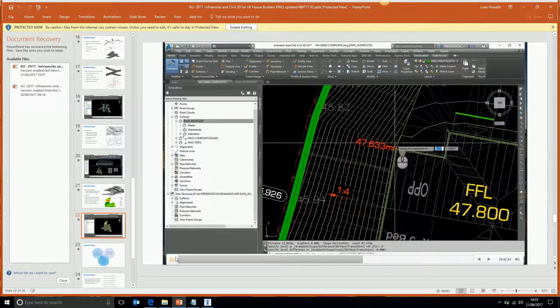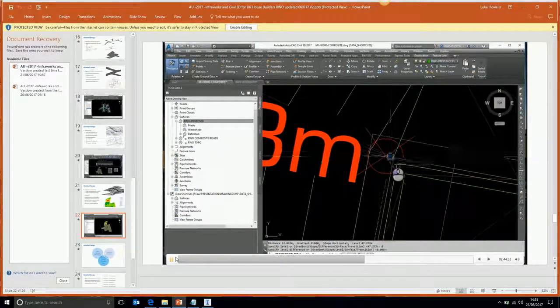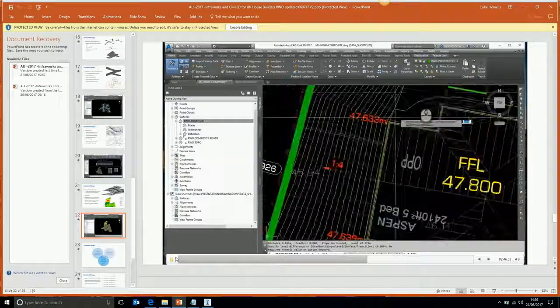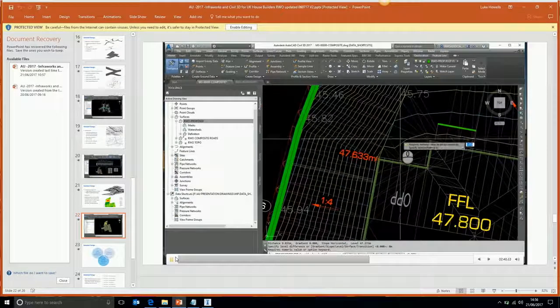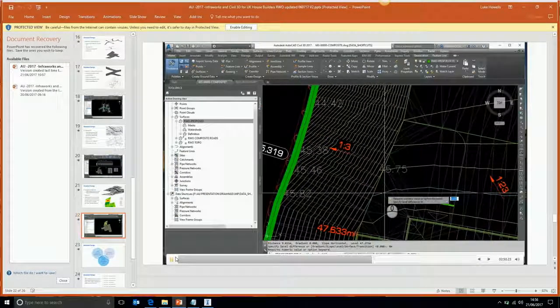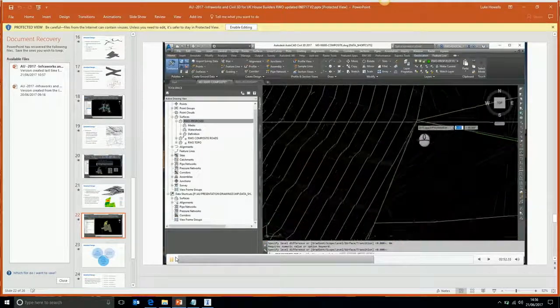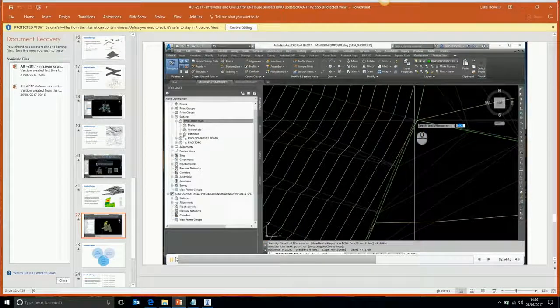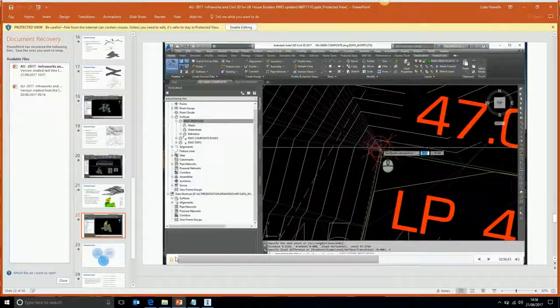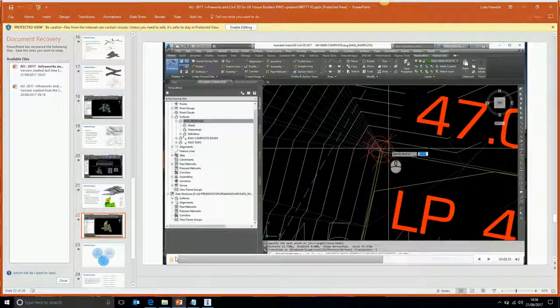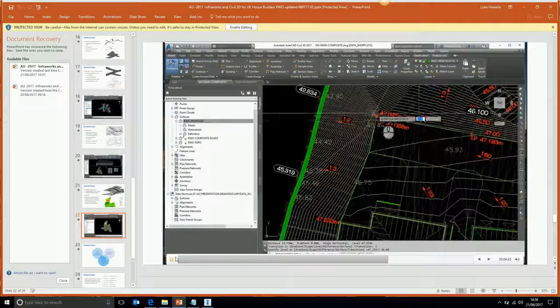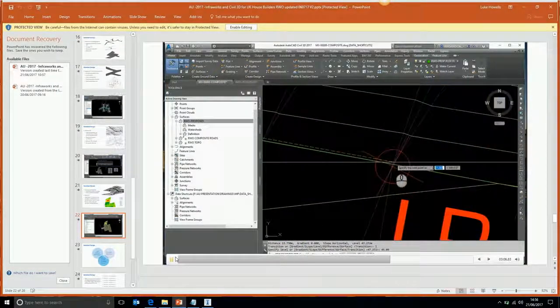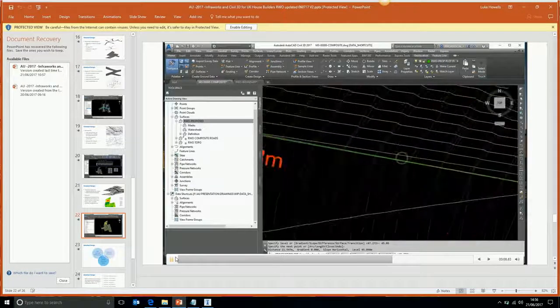Give that a level, run it along to the other side of the property, and then we'll actually have a little bit of a private drive here, what needs retaining as well, so we're just going to step that feature line around the side of the private drive, try and get away from that 1 in 3 gradient, which 1 in 2 gradient there, which is a bit steep really for a landscape area. Just entering another level there on the feature line, then we'll bring that just to tie back in with the proposed surface.